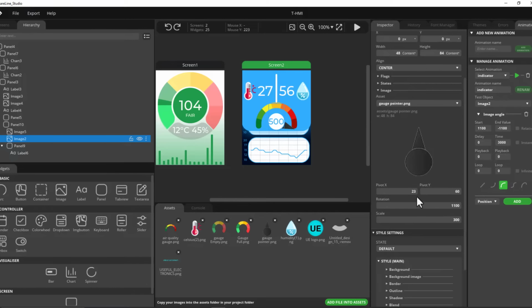So let me show you what happens when we use the default values. Let me move this to here, and I will use the default values, remove the rotation. Now when I try to rotate this object, say that I want to rotate it 90 degrees, you'll see that the whole object moves because the center of it is located over here. However, the center that we are aiming for should be over here.